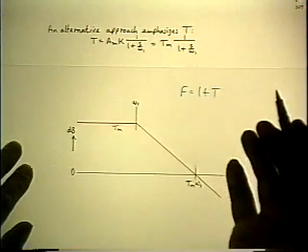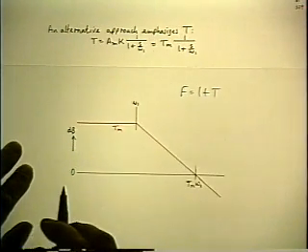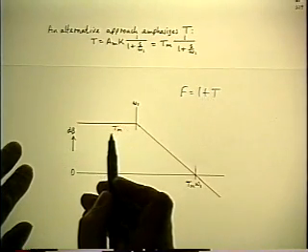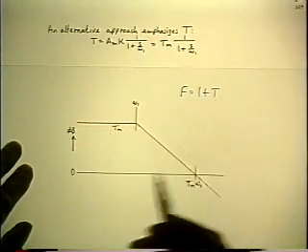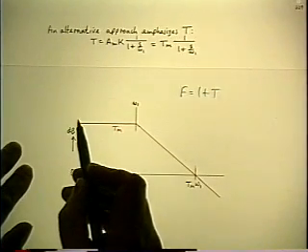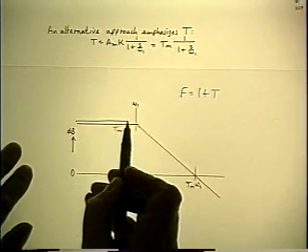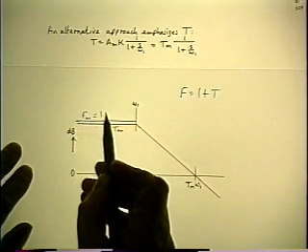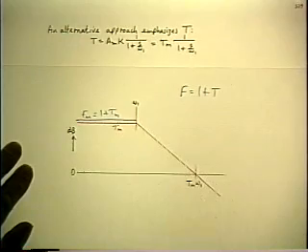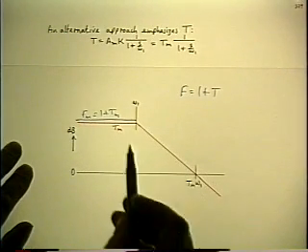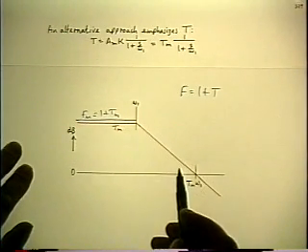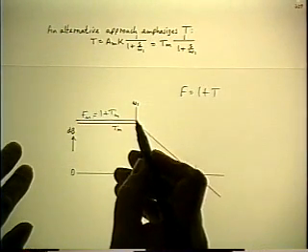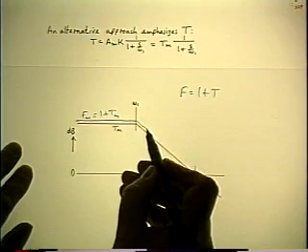One of the functions is only 1, but nevertheless it's a function. Okay, down here T is large, so F is going to be just a shade bigger. So I draw another line down here just a little bit above this one. I label that one Fm for midband value is 1 plus Tm. As T goes around the corner, F will go around the same corner because it's still just a shade bigger than T, as long as T stays large.